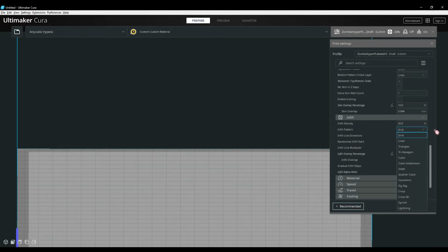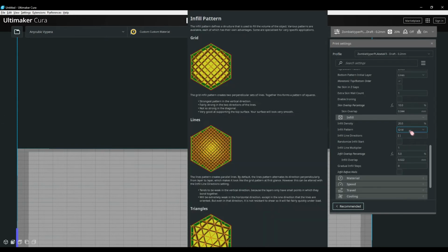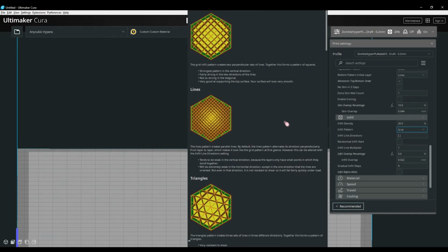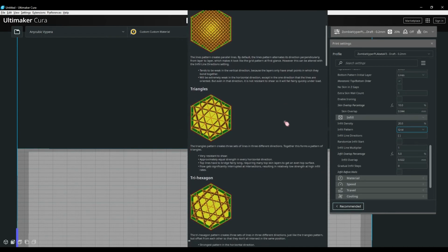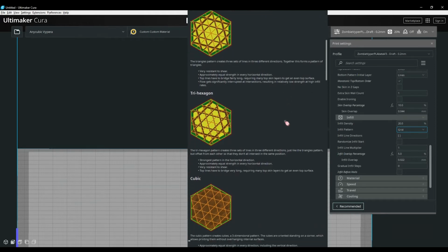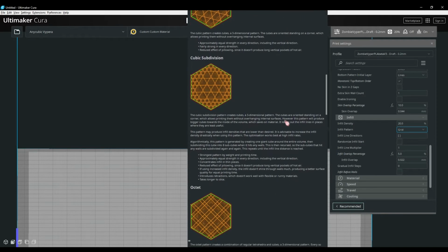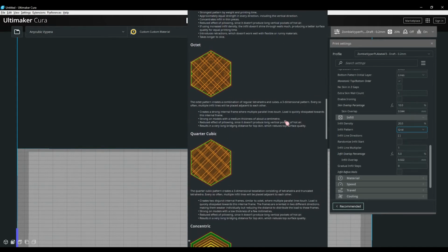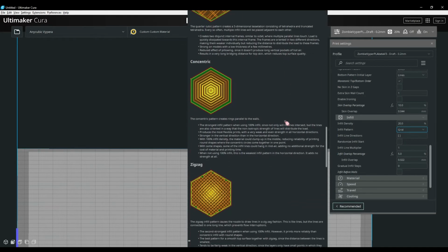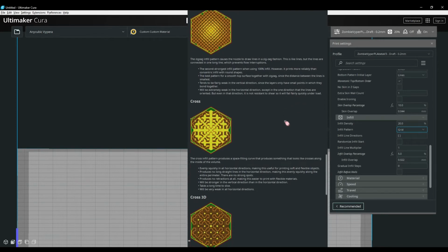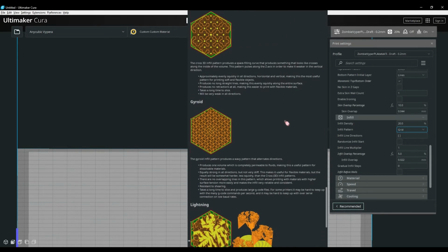You also have the option to randomize the infill start and infill before walls. This is also where the gradual infill step option is. For some of the patterns, what it does is increase the infill density the closer it gets to the top. For example, if you set the infill to 90% and have 5 steps, the top of the print will be 90% infill and the bottom will only have 2.8%, making the top stronger with a cleaner finish.